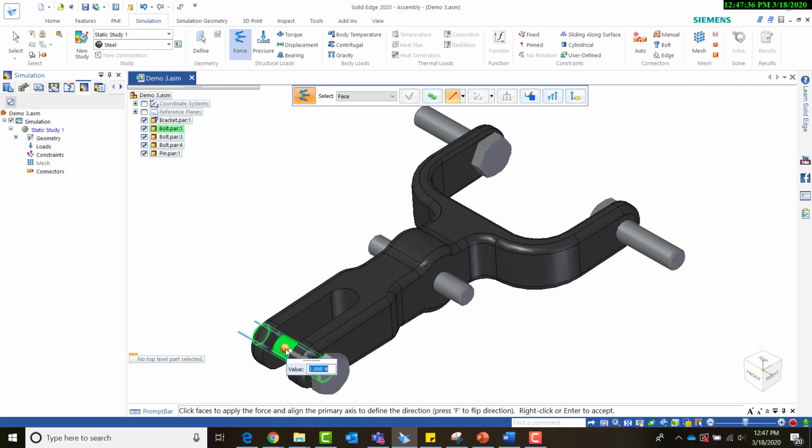And I can grab the steering wheel to help define the direction of my forces. So I drag that to a flat surface on the top, and we can see how my arrows moved. If I drag this to the left or the right side, you're going to see the arrows move as well. I do want it to go downward.